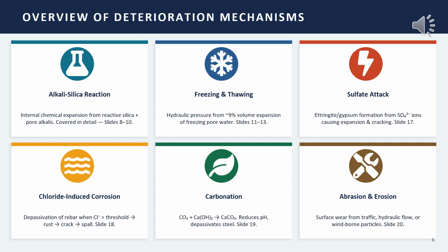In practice, these mechanisms rarely act alone. A bridge deck in a cold climate, for instance, might simultaneously experience freeze-thawing cycles, chloride penetration from de-icing salts, and carbonation of the cover concrete. Each mechanism weakens the concrete in ways that accelerate the others.